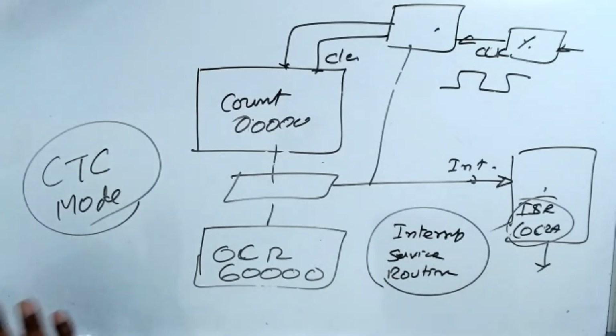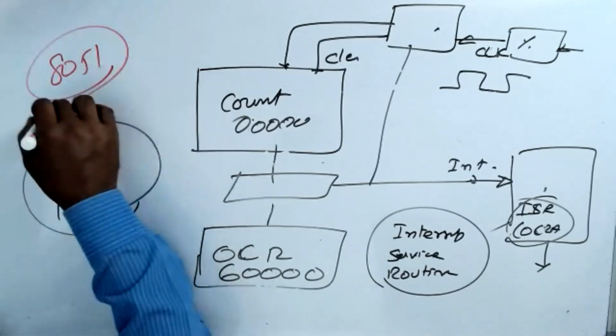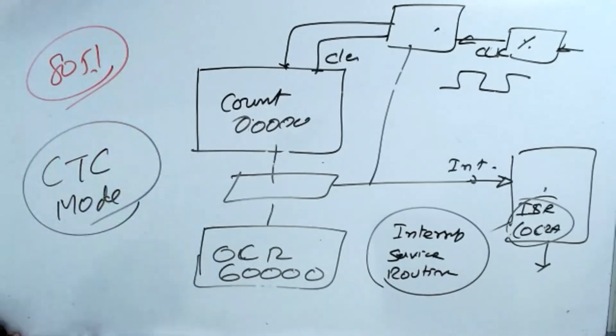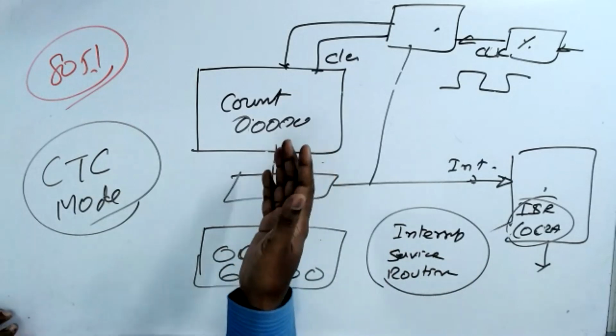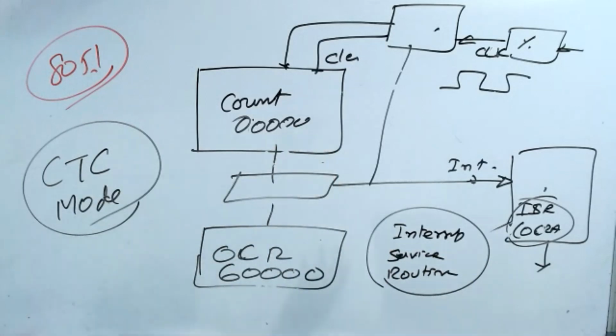About interrupts, we will have another session on interrupts and DMA. Those are to be understood by you as a part of the system. I have explained a very, very simple timer operation. Nowadays they make it simple. If you take the 8051, the timer is very simple, not much. But if you use this ATmega 2560 chip, it has too many options. It has six timers. You can use them to control so many motors outside. When it comes to motor control, we will discuss that.